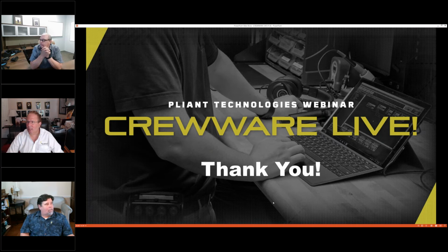We have one more question. It just came in. Does the sync connection need to be connected the entire time the two systems are in use? And yes, the answer is definitely you want to do that. You want to maintain sync. It's actually a good practice to even synchronize two different systems that are in the same area, but at different frequencies. So even though normally you wouldn't worry about a 900 and a 2.4, there are harmonics, and desensing is a real thing. It probably doesn't make a massive amount of difference, but as best practice, it's good to synchronize everything if you can.